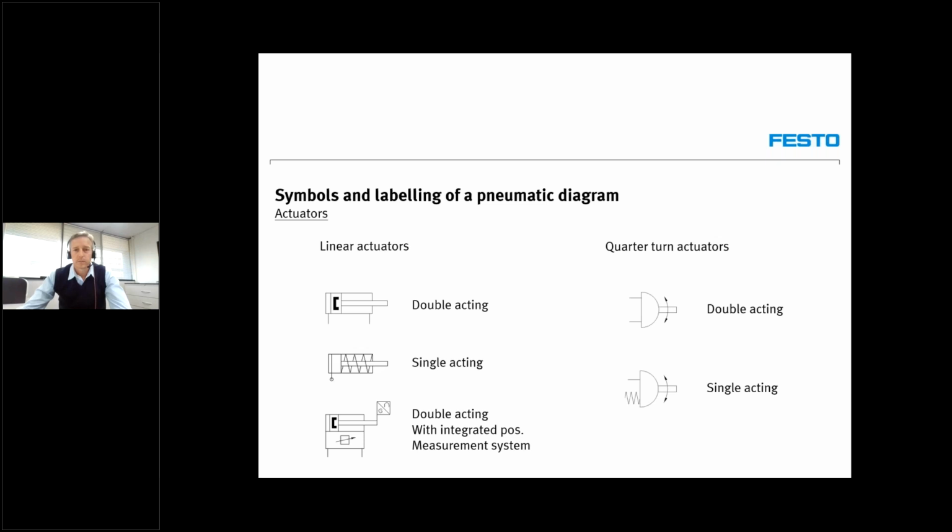Or else, while the equipment is running, we have audio equipment, sometimes referred to as a sniffer, and you run it along all the joins and along the lines and all the connectors, and you can actually detect where the leak is with this little audio amplifier. So maybe that's a bit of background of interest there, Russell and Hannes.